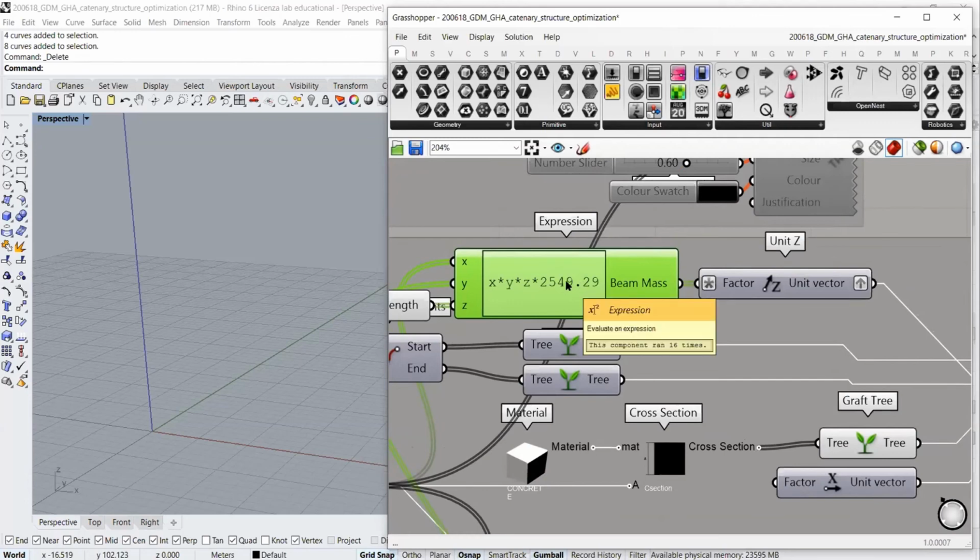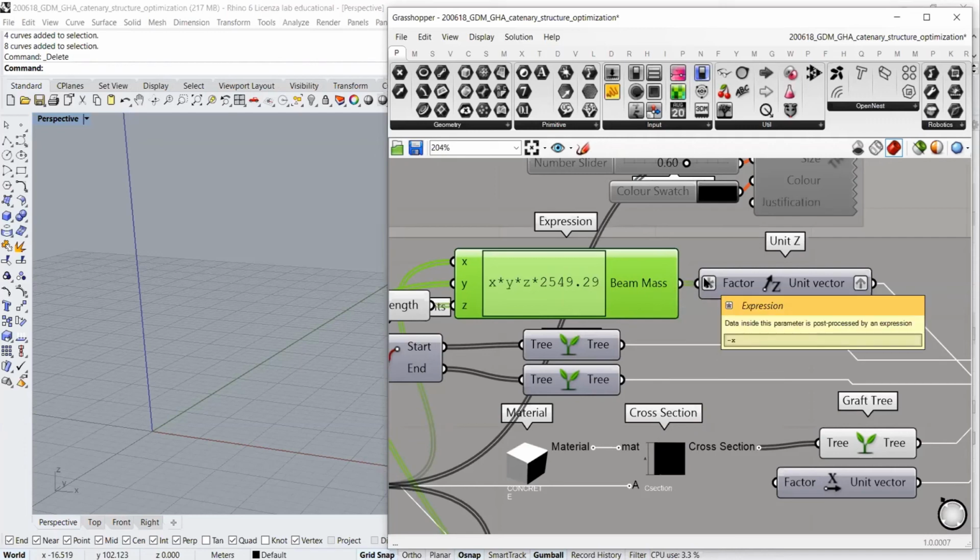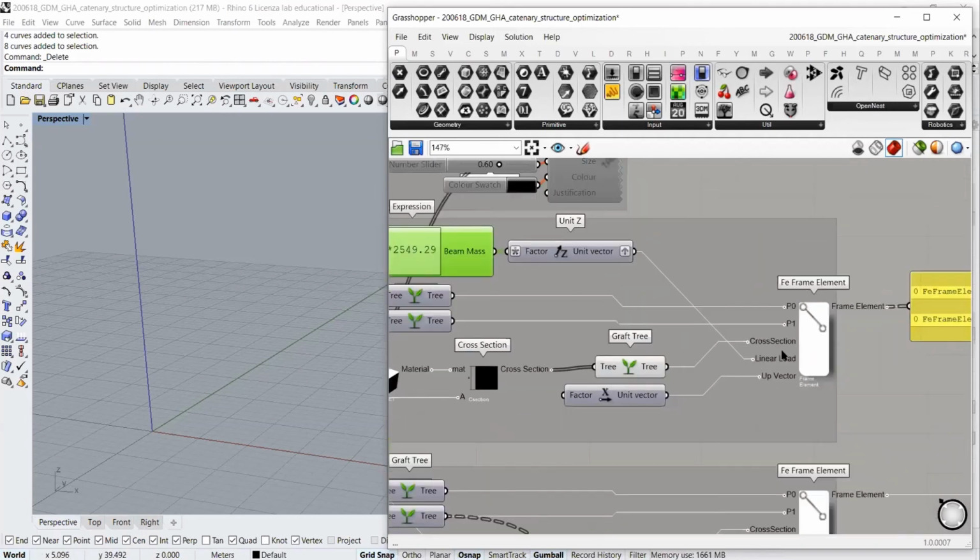I'm not considering, in this case, the iron bars or reinforcement bars and so on. This is an ideal thing that I did here, but you can be as precise as you want, of course. Normally, you might want to use some percentage in order to come up with an average weight of a reinforced concrete beam. Normally I would not recommend being too analytical in this phase. So the beam mass is this value, and this is inverting this value here, so it's going to be applied in the vertical and negative direction, and it's going to be used like a linear load.